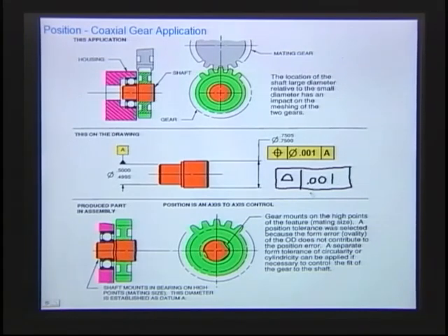And the reason I don't think you could, in relationship to A, is you see this size over here? Make that a little bit bigger. The size is 0.7505 to 0.7500. And the reason that tolerance is so tight is because I need it that tight to be able to fit inside of the gear. That was a press fit on the gear, so I need this size. It's a size that I need to give it a press fit, tight.